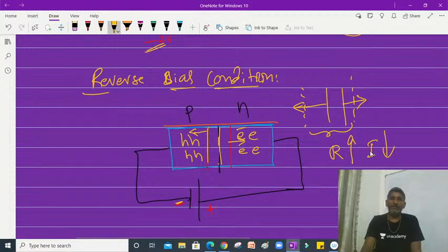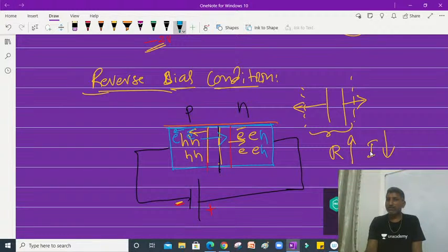In this also, again you see. Now you can say, sir, what about current in this reverse bias condition? Whether it is zero or something else? Yes, something else. Some current will be produced here. Due to what, sir? Here, holes are the majority, but electrons are also present. Electrons are minority here. Minority means less in number. Here holes are minority, less in number. But these electrons, having negative charge, are repelled by the negative terminal, so they can cross. Holes are positive, so they can cross.